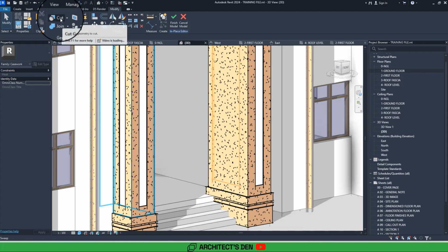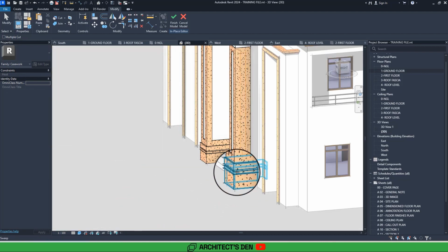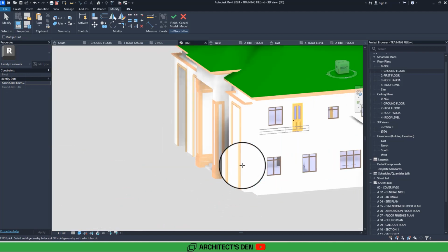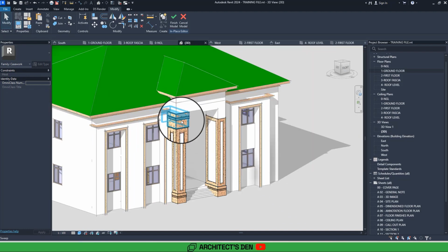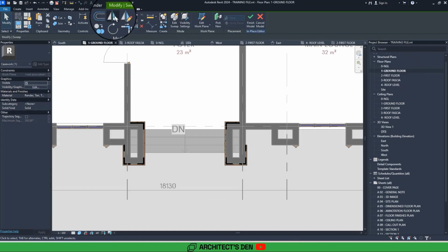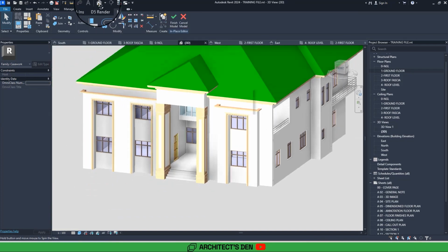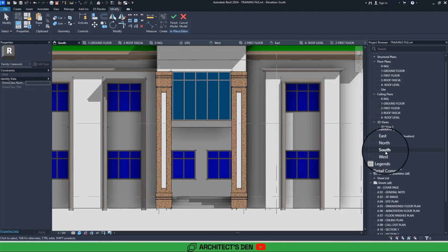So what you do, you can just select this cut geometry icon here, click on it, select the cut pattern, select the element to recut those ones that did not cut. So you see we have this. I forgot to mirror this particular one, so I'll go down, select it on my ground floor. I can also use pick mirror axis because I know this is the center and it's also going to mirror it.